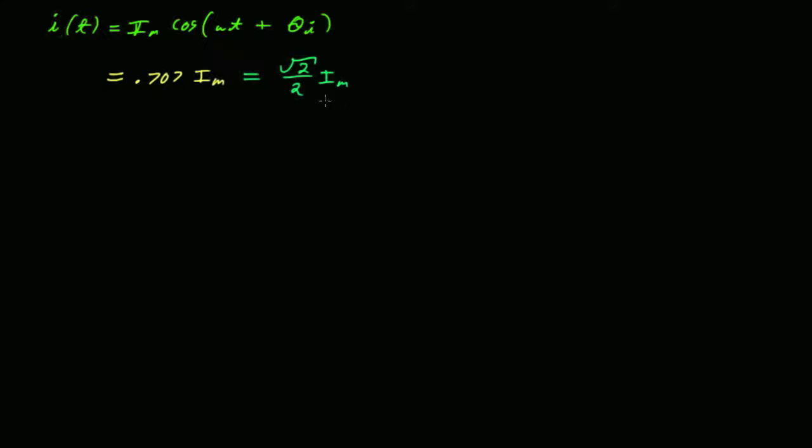So a lot of times when it comes to power especially, we don't talk about the peak voltage of a cosine. We talk about its RMS value. It's sort of like its effectiveness. So we talk about the power outlets: it's 120 volts RMS, right? It's not peak to peak. It's RMS, and that's essentially just giving you its effective power.